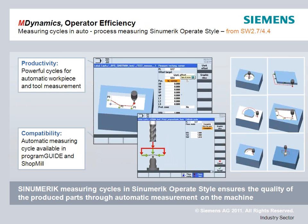Back to the measuring cycles we were talking about. Some of the more exotic measuring cycles, we have taken a few screenshots and put them off to the right. The idea is that now if we have to locate the center of a circular feature where we have a side locked off, we can do that by locating a handful of points on the circle. We don't need the entire boss or hole to be present.